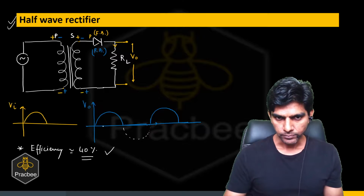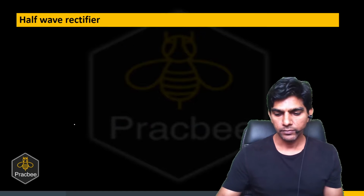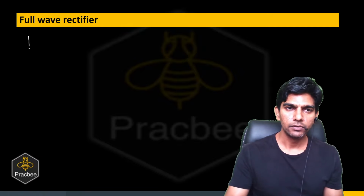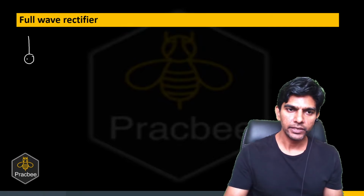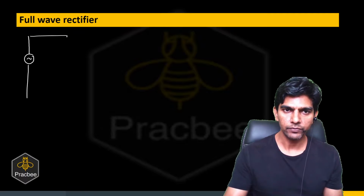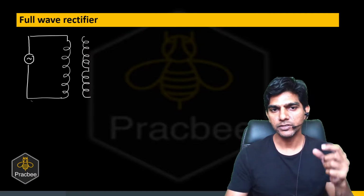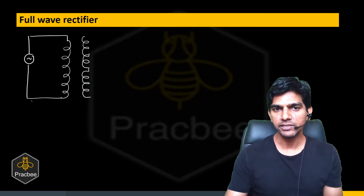Now, let us see a full wave rectifier. So again, we'll feed an AC supply to this rectifier, and again we have a transformer, but now we are having a special transformer. It is known as a center tap transformer. In center tap transformer, the secondary winding is made up of two parts. So we have two coils in series,